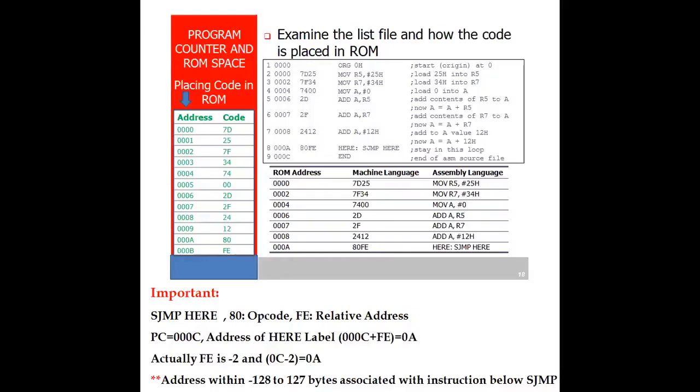You know that the microcontroller provides the ROM memory to write the program. I mean, I can run the program inside the ROM memory of the microcontroller. Okay, so when the microcontroller is powered up, the program counter has the value of 0000 in it. So therefore, it is always expected that the first opcode is stored at the ROM address location 0000 hex.